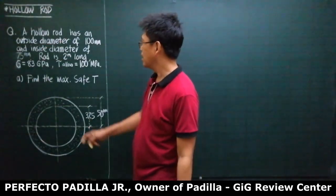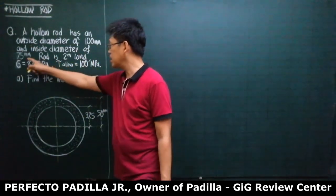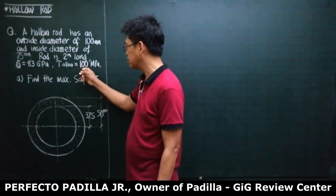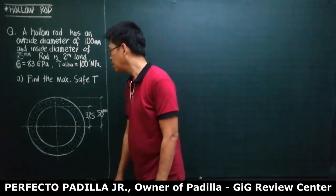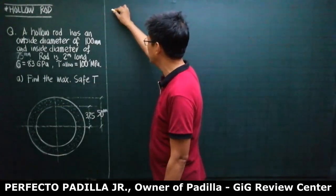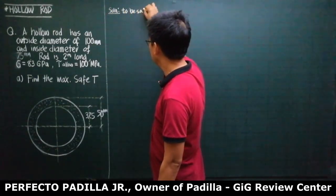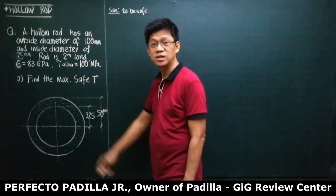A hollow rod has an outside diameter of 100, meaning radius is 50, and inside diameter of 75, meaning radius is 37.5. The rod is 2 meters long, G is 83 gigapascal, allowable shearing stress 100 megapascal. We are asked here to find the maximum safe torque. If maximum safe is being required, then we use the equation of safety. The equation of safety simply says, in order to be safe, there is only one allowable stress given, that is the shear stress.